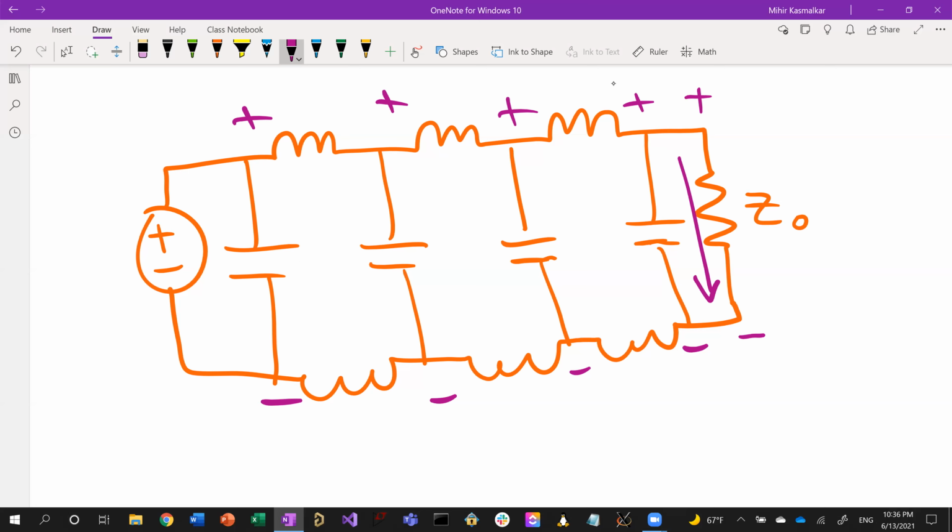And so this transmission line is matched. You don't see any reflections coming back from this transmission line. The incident wave is sort of absorbed at this resistor, and the resistor just keeps drawing current. And so that's this third case where the transmission line is matched.